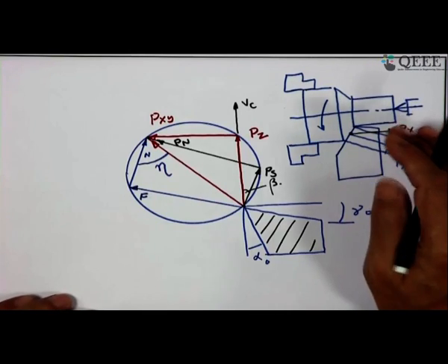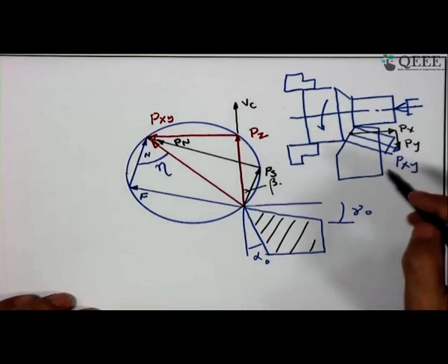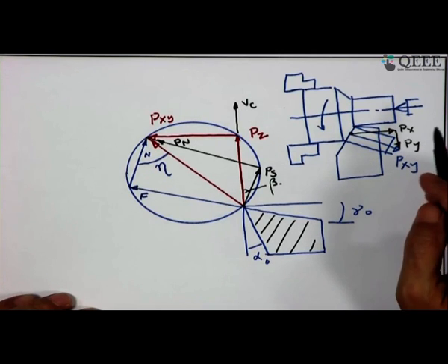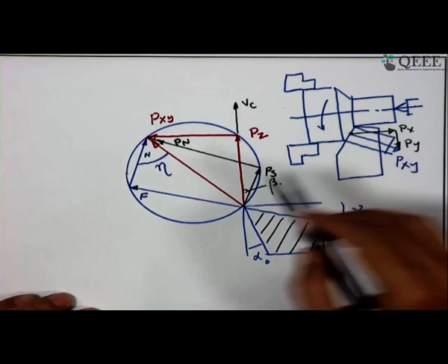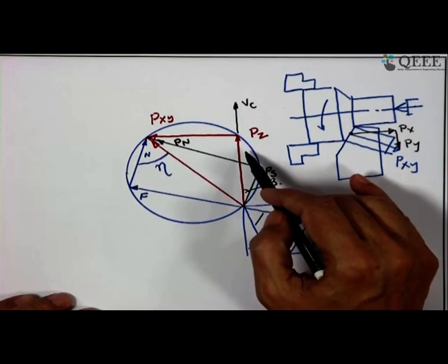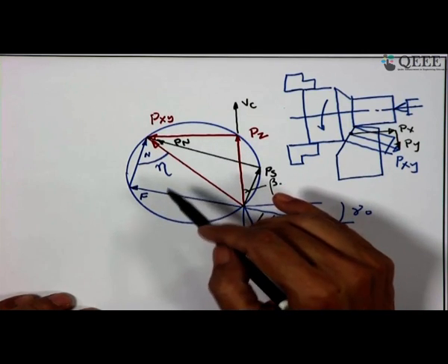We have similar coordinates for milling machine, drilling and other machines. So, accordingly, if you place the dynamometer, we can measure Pz, Pxy, and then from Pxy to Px and Py, and from there we should be able to establish a relation between these measured quantities or known quantities and those which are to be determined. Okay.